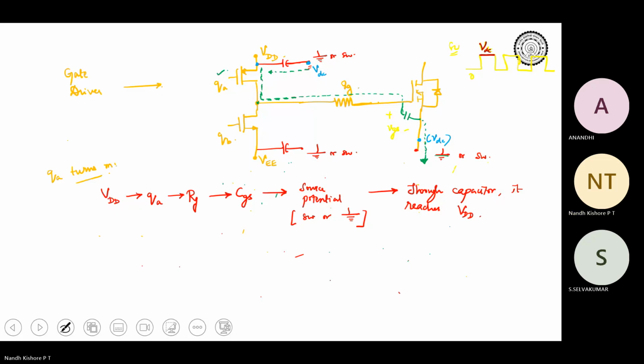Okay, so as far as the gate current is concerned, it will come over here. It comes like this. It has come over here. It is seeing VDC voltage over here, and it has a direct connection through this capacitor back, because this capacitor is also at VDC. It doesn't matter whether it's at 0 or at VDC, because this potential and this potential are going to be the same. Do you understand? The potential is the same. That is what the current wants.